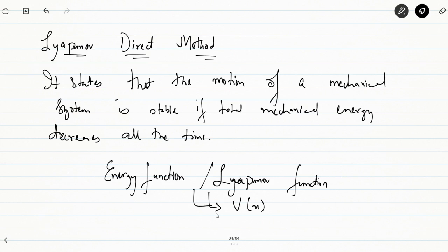We'll start with the Lyapunov direct method by defining it. We'll put forth different definitions of the Lyapunov direct method for analyzing the stability of the system, be it asymptotic stability, exponential stability, or global stability. The Lyapunov indirect method was only confined to the local stability of the system, but the Lyapunov direct method will consider the global stability of the system.